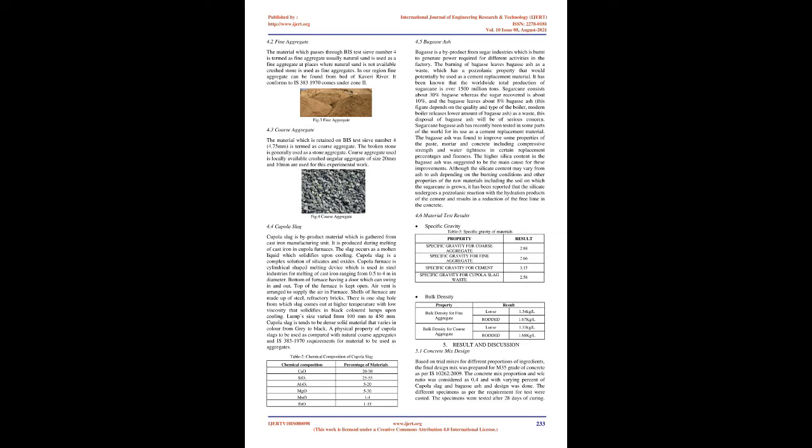It could be said that 100% replacement of normal crushed coarse aggregate with slag aggregate improved the flexural and split tensile strength by about 6% to 8% in all mixes. The improvement in strength was attributed to the rough surface texture, which ensured strong bonding and adhesion between aggregate particles and cement paste. In case of natural fine aggregate replacement with slag fine aggregate, the strength increased for 50% by 5% to 6% but reduced at 100% replacement by 6% to 8%.